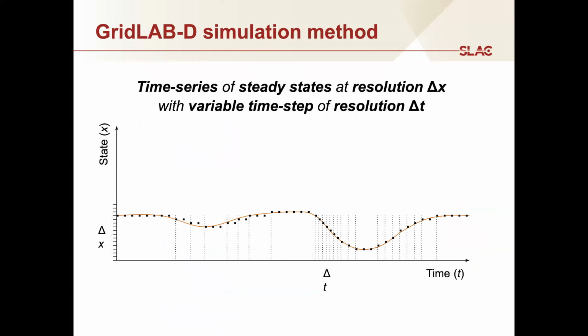Well, fundamentally, every object in Gridlab-d has to answer two questions. It has to say, what is the state of the system at a particular moment in time? So think of it as the forward function of time, and identify any changes in those states given that time advances.